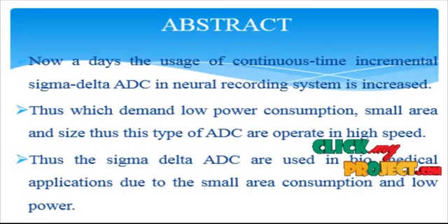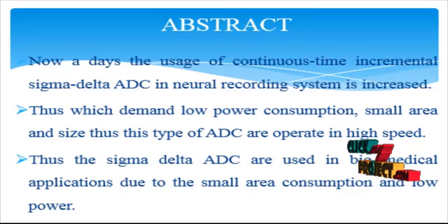In this paper, we take a step further, proposing a more power-efficient sigma delta alternative for high-resolution multi-channel A to D conversion. The proposed design combines the speed of a pipelined ADC and the resolution of a sigma delta ADC, and by the sigma delta pipelined ADC stage, high resolution can be achieved with high density of ADC based processing.